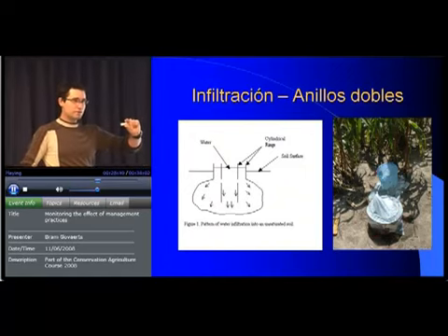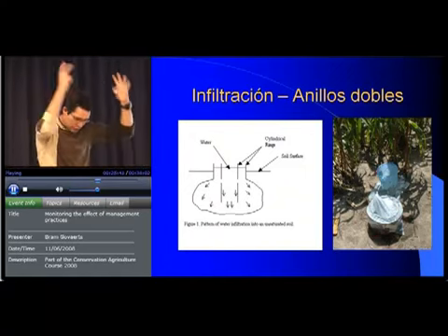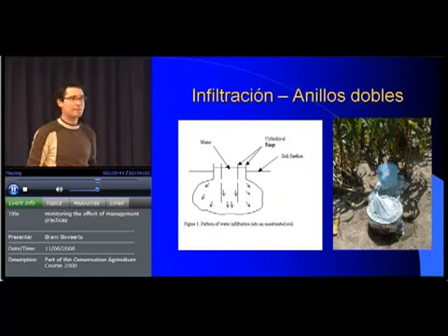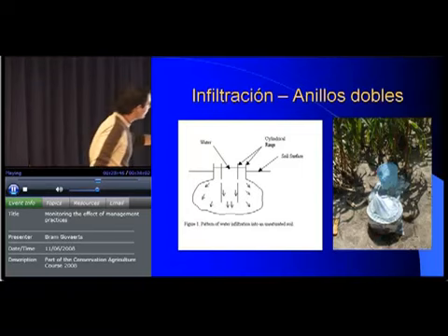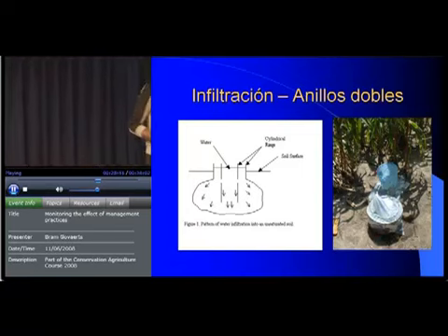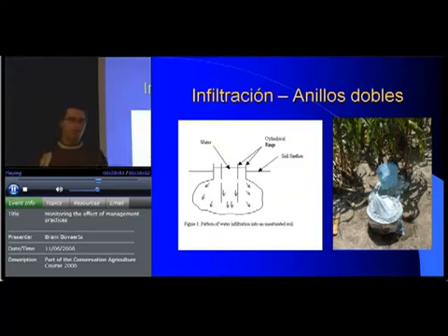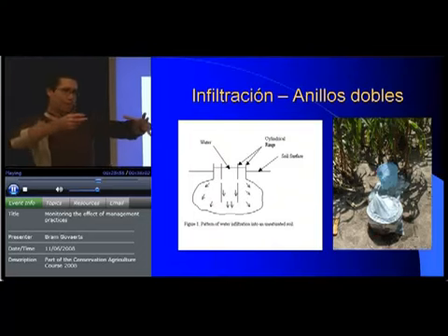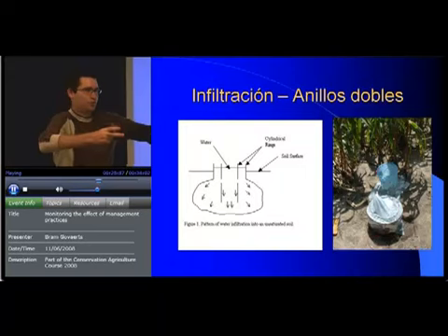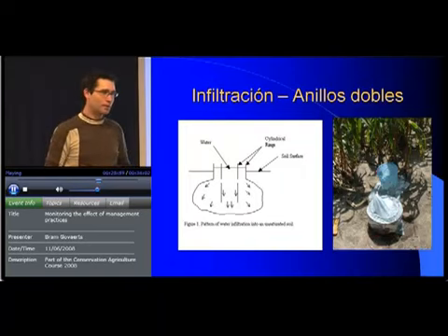You have a crust. Now you're going to put the double rings there, and of course you have to get them in the ground. Because the double rings, you can see, they have to be like 15 centimeters into the ground. So, if you are fancy, you buy a kind of pressure plate and you press it into the ground. If you're not fancy, you just drill them into the ground.